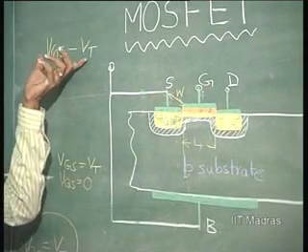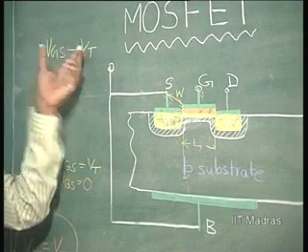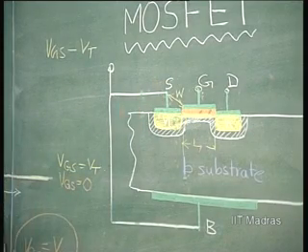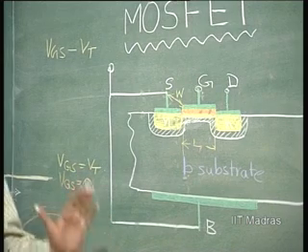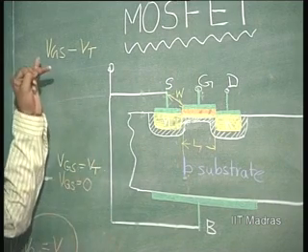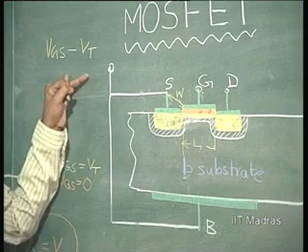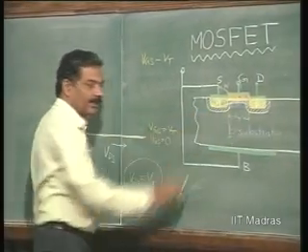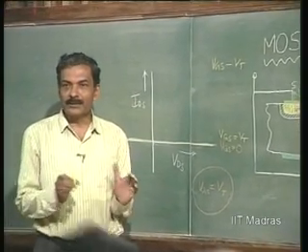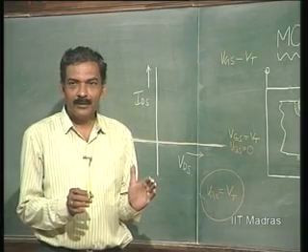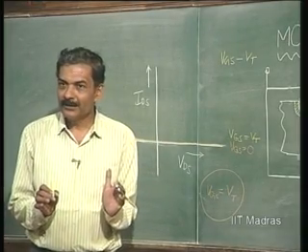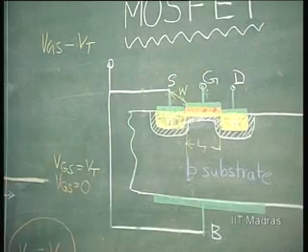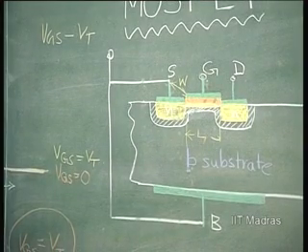So, depending upon this, if this magnitude is higher, this depth would be higher. Therefore, what can we conclude about the resistance now? That the resistance keeps on decreasing as I apply higher and higher value of VGS. That means this channel is really equivalent to a resistance as long as VDS is kept close to 0, and this uniformity of the resistance depth can be stuck to.